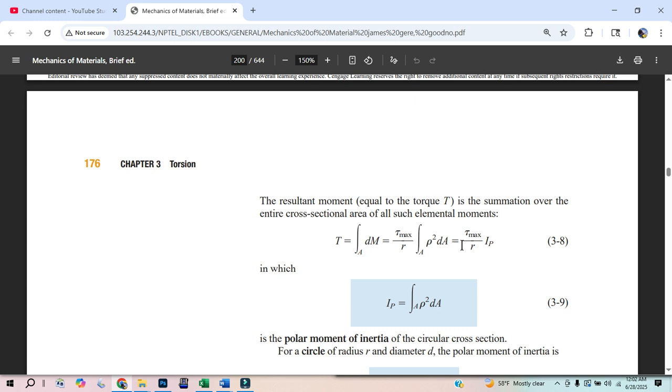I would just think of a number that is between 0 and some sort of max the material can take, which is usually the yield stress for design purposes. You don't want to get into making your bar plastic, but I could weld that solid cylinder to the wall, torque on it, and know that it's going to get tweaked, and maybe feel that it didn't get bent. And then I know it's within that limit.